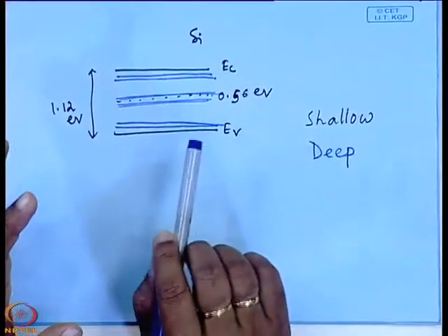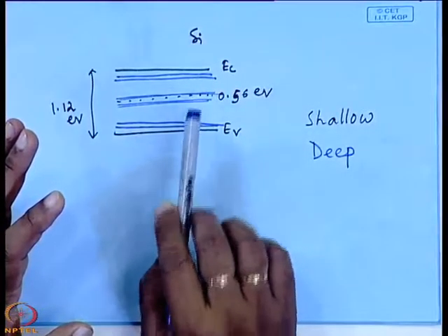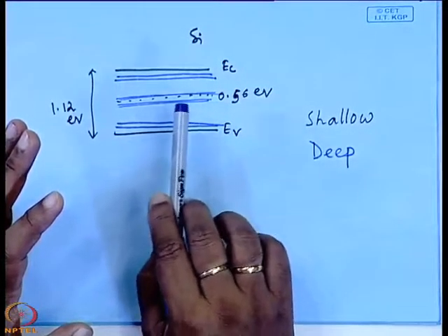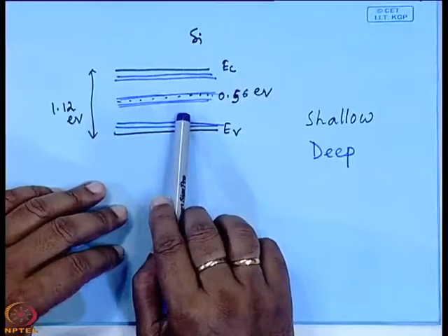So, that is the conduction mechanism in a semiconductor, but the deep levels will not contribute to either electrons or holes, because the position they occupy is very deep as far as the conduction band edge or valence band edge is concerned, and consequently such a huge amount of energy will not be provided.